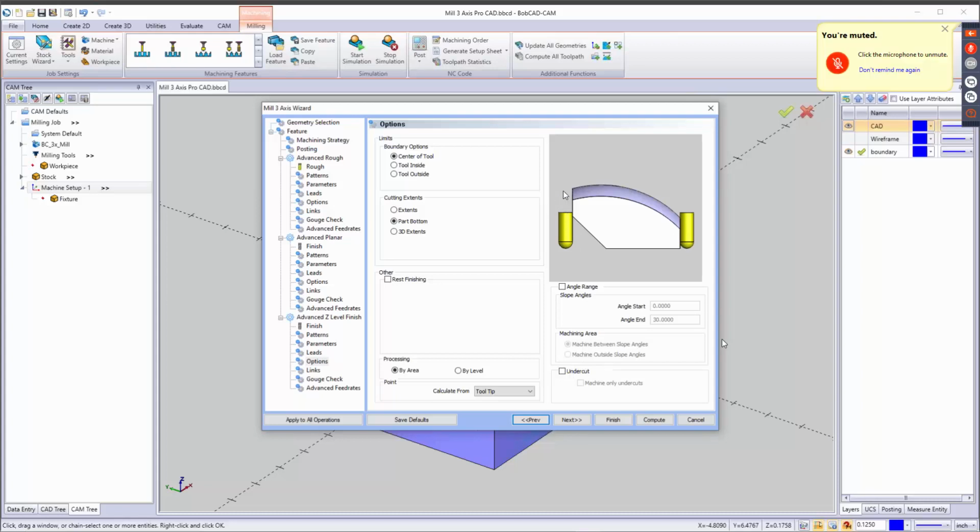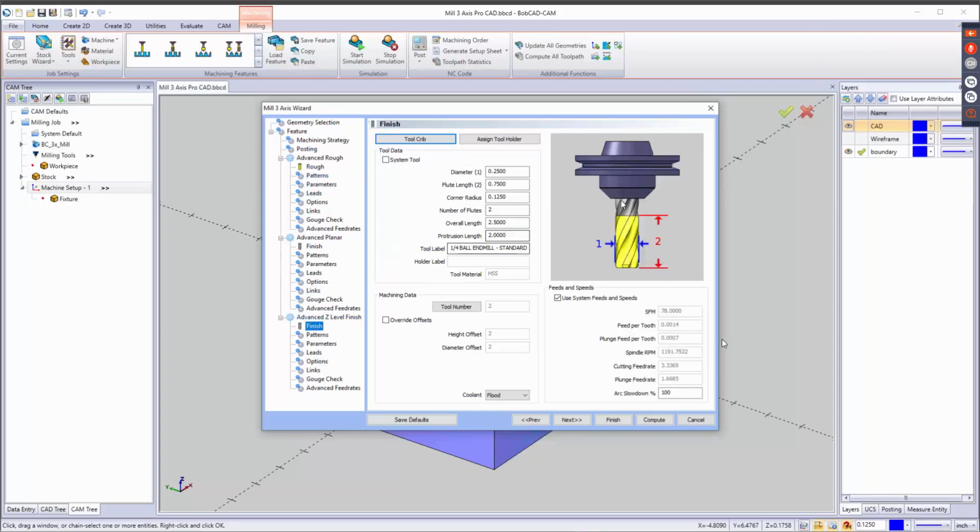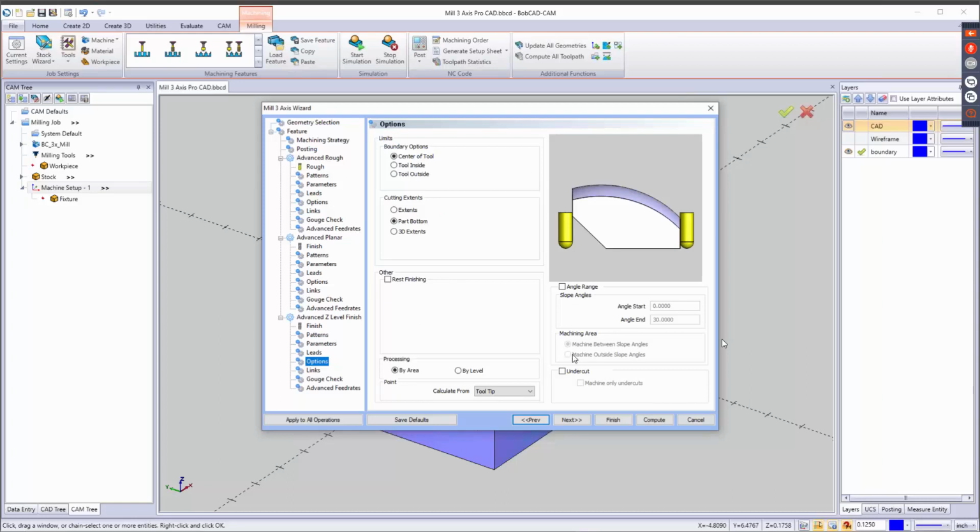Now, it's only going to do the undercut as wide as the diameter of your tool here. Not the flute length, whatever is sticking up in the holder here, it's only going to be that wide. I can't even think of the word it's using. Anyway, so be careful of that one. It does work nicely. Just be careful. It's only going to go as wide as how much is in the holder there.